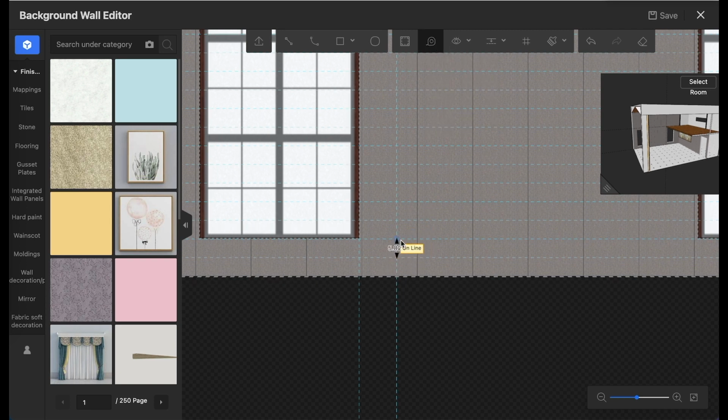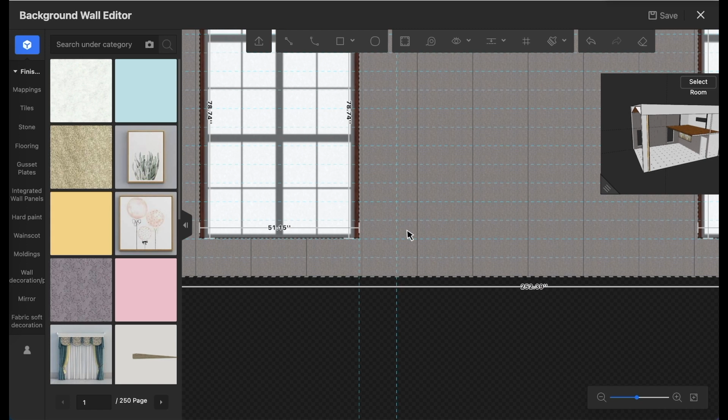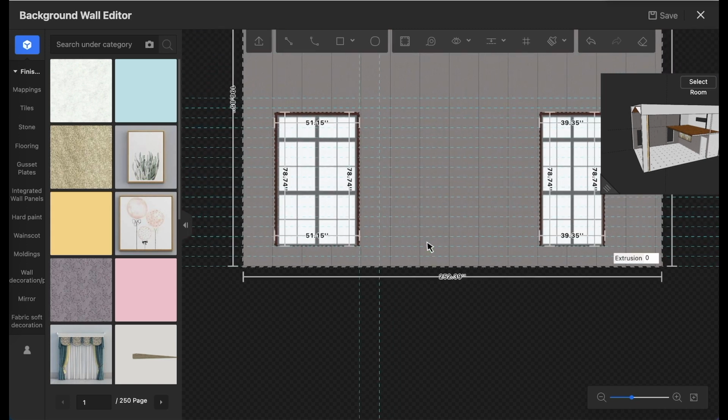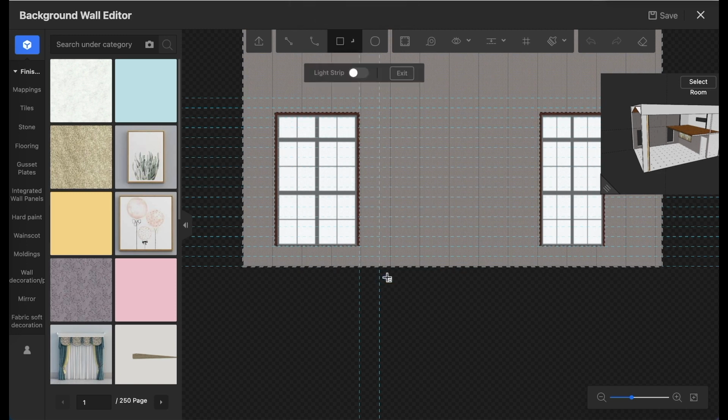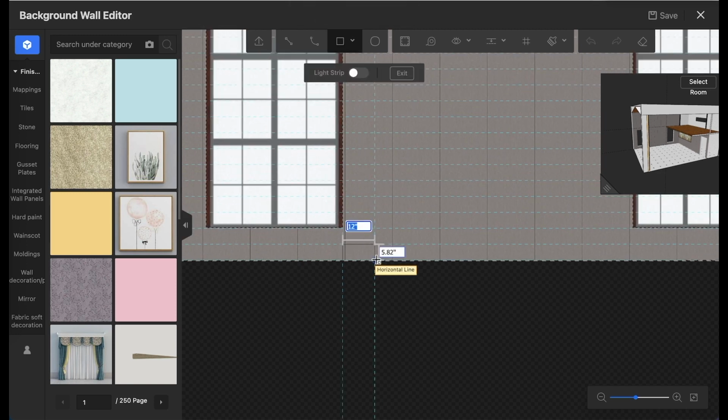So then we can actually measure the width of different stairs just to make sure that it is 5.82. So that is the number we're going to hit. If you happen to only have one stair, or if you intend the stair to be only fully attached to the side of the wall, which is not our case here, you can directly model the thread here, which is quite convenient using the extrusion tool.